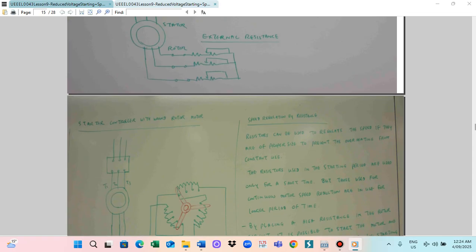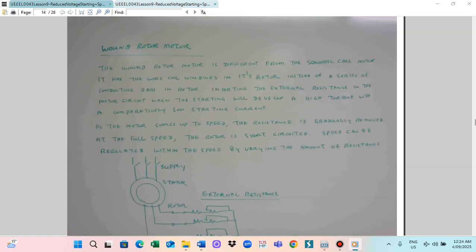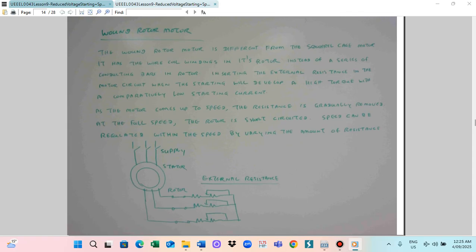So for the compressor motor, the force at compressing and release times is different. At this time the force will be the maximum, then this one releases and goes back this way, and the force will be the minimum. The force changes between maximum and minimum very frequently. In that kind of situation, the motor can vibrate.